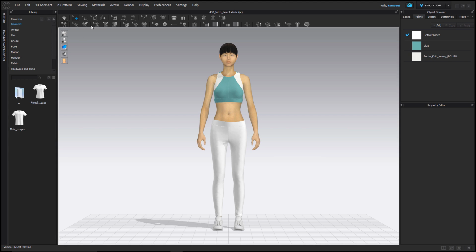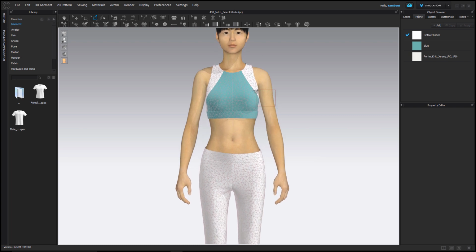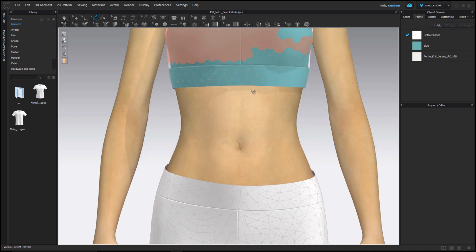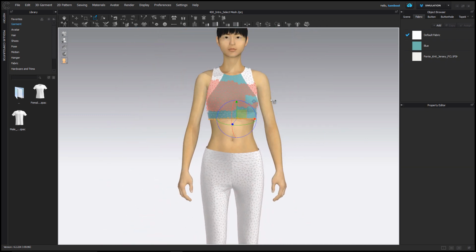Similar to the mesh tool, use the pin box tool by marking selections you wish to pin. Click and drag over an area to apply pins. Pins will appear as red dots. Hold Ctrl and marquee over areas to remove pins from the selection, and hold Shift while you marquee to add a selection. Double-click the edge of a garment's mesh to select the whole edge.